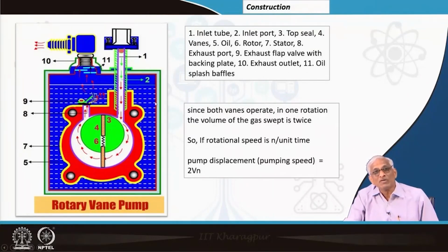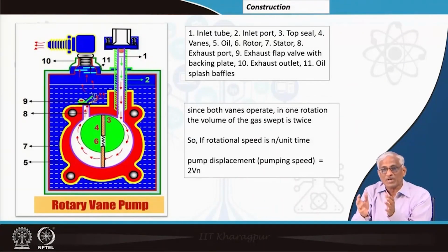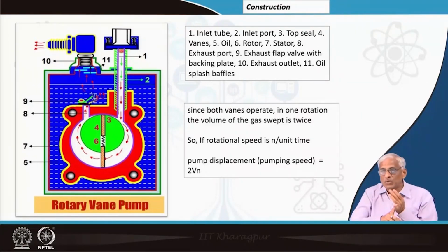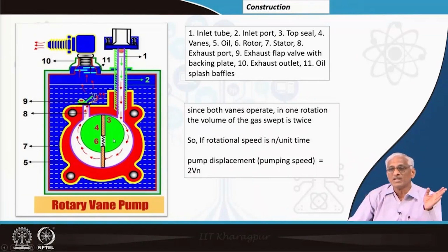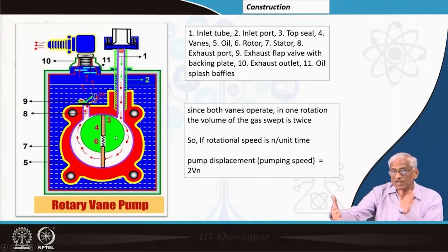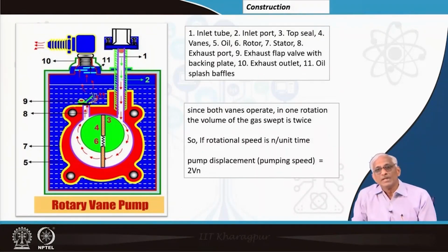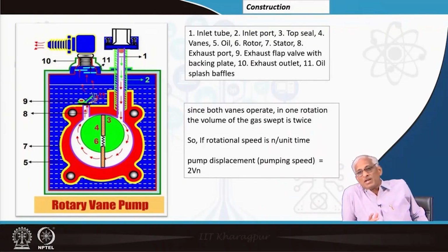This oil will act like a coolant, because this is a relatively high pressure, there will be heat of compression, and that compression heat should be removed, otherwise seals will be spoilt after some time, after 1 hour of running. It will also act like a sealant, because the entire structure is working under vacuum conditions. Atmosphere will try to rush in through any possible leaks in the integrating of various subparts of the rotary pump. It is not an easy job to make a leak tight pump. So you require an oil which is acting like a sealant also.